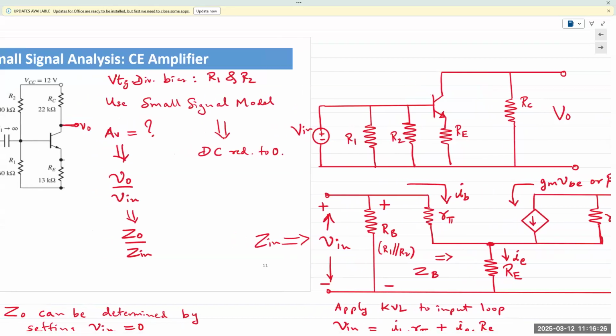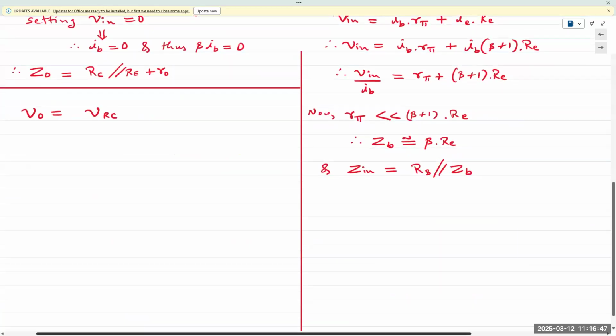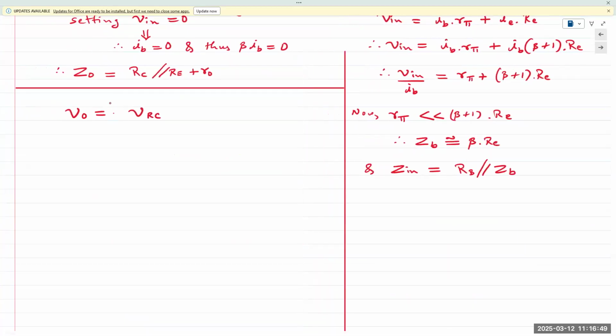All right. If I label this as X and I label this as Y, where is X and Y in this diagram? Is X at the top or at the bottom? So X is here, Y is here, right? So RC is flipped down. So the magnitude of VO and VRC remains the same, but the sign would be opposite because you are now measuring opposite polarity.